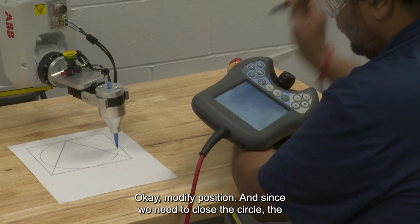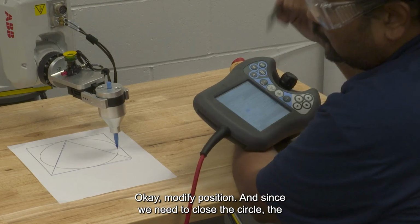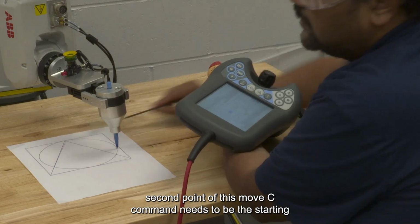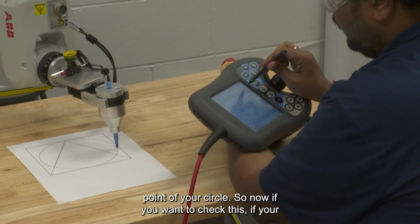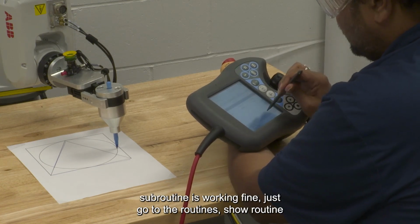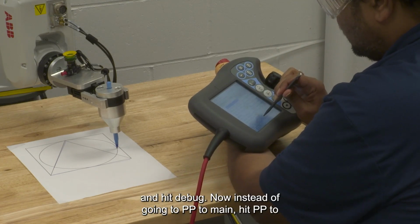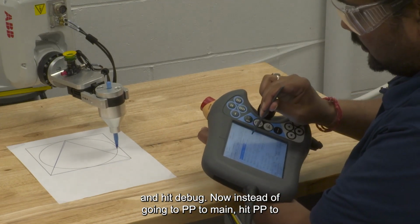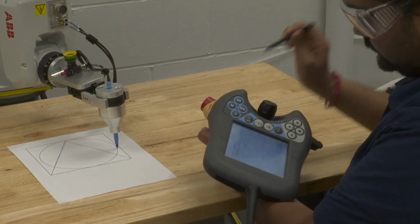Okay, modify position, and since we need to close the circle, the second point of this move C command needs to be the starting point of your circle. Now if you want to check if your subroutine is working fine, just go to the routines, show routine, and hit debug. Now, instead of going to PP to main, hit PP to routine, and you have to select the circle.